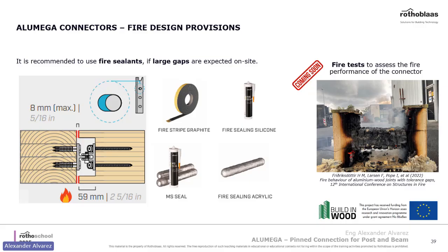The reason we have 1 hour and 2 hour fire ratings is that after the fire, you want to make sure the connection is able to stay up. It goes for anything like a steel beam. You want to make sure it is structurally safe even after being burned up. If you heat up a metal, you may notice it becomes very ductile, very bendable.